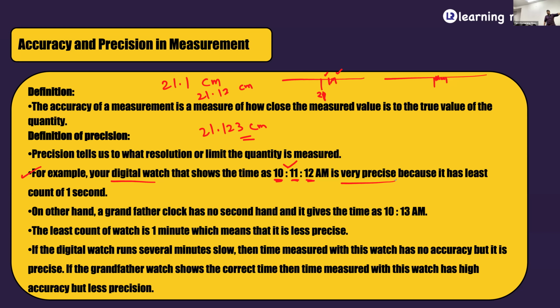So that's how it is helping. For example, what is the least count I'm able to see in this first one? Look at the last digit. It is 1 millimeter. What about this? 1/10 of a millimeter. Here I'm able to say 1/100th of a millimeter. This is more precise. It means that if such a device exists, between 2 millimeter lines you would be able to see 100 lines. It's very, very difficult for us to see that with the naked eye. That is why they will not devise something like that.